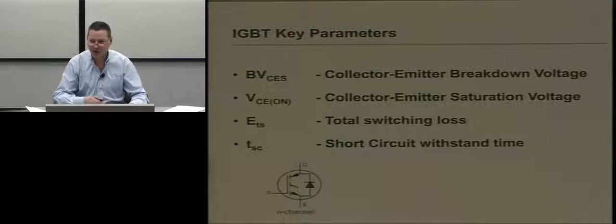So universal power factor corrected line is in that range, usually 380 to 400 volts. At higher voltage, when you rectify 480 volt three-phase, you have a 700 to 800 volt bus. So the devices are rated at 600 and 1200 typically.